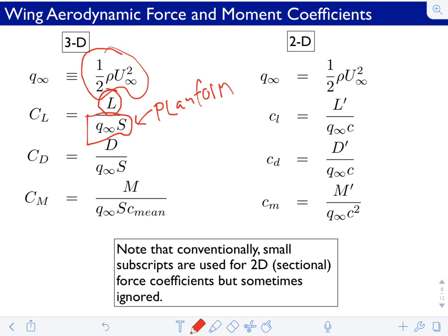It's not a cross-sectional area. It is not the surface area. It's roughly half the surface area. So if you take the upper and lower surface, that's your total surface area. This is essentially half of that if it were pretty thin. So just be cautious about that. That is just the tradition that is used for computing the lift coefficient.